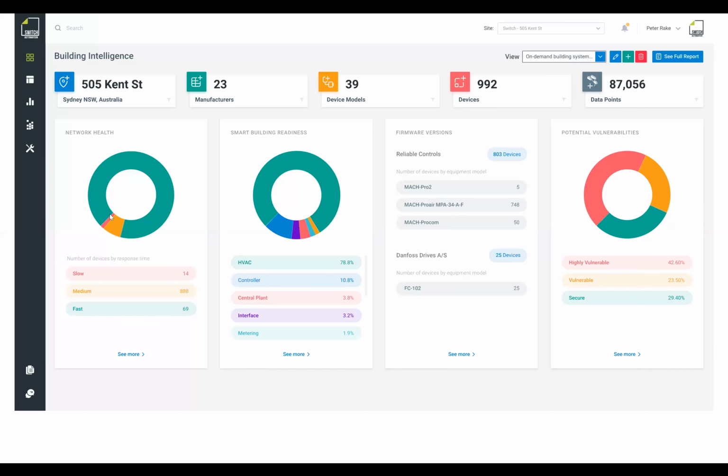So the common way that we're able to uncover any of these issues is by running this network health check, understanding if there is some slow response times to controllers, because it's not the visual layer, it's the underlying controllers, which you typically do not have visibility into today. So this is going to highlight any controllers that need replacement, or the comms cable between controllers is compromised.